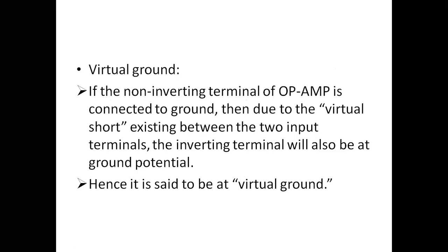And if we connect the non-inverting terminal, the positive terminal, to the ground, and we make the virtual short at the two input terminals of the op amp, at that time its inverting terminal will also work at ground potential. So we can call this concept a virtual ground.